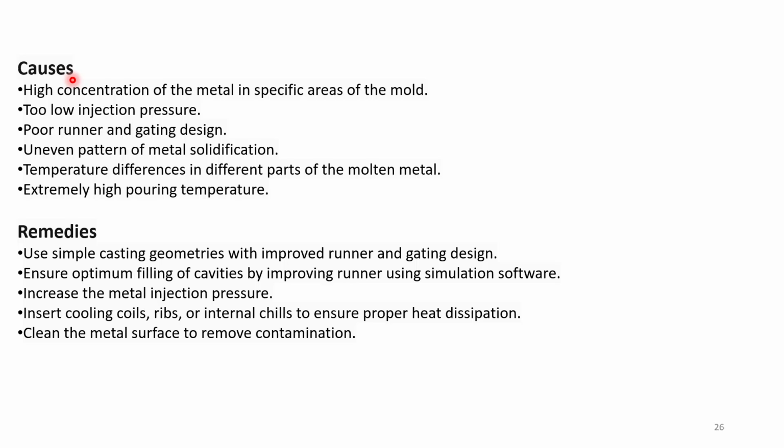Causes: a high concentration of metal in specific areas of the mold, and too low injection pressure. In case of sand casting, the pressure is less compared to pressure die casting or other castings. Poor runner and gating system: if the design of the gating system is also not proper, then it may lead to lower pressure and entrapment of gases, and also shrinkage. And an uneven pattern of metal solidification.